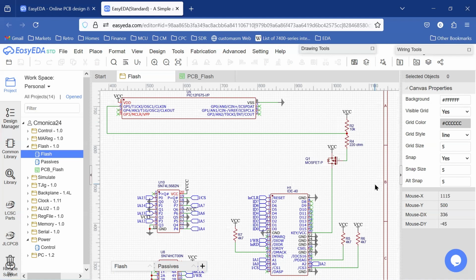But with our soft start power supply, that's going to be less than 5 volts for 200 milliseconds. So to make sure that we are presenting a solid 5 volt source to the compact flash card, we need to do something special.